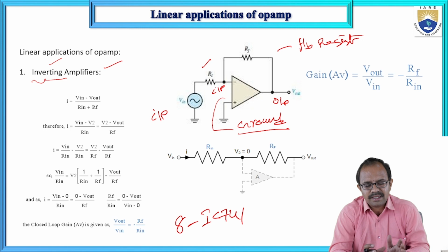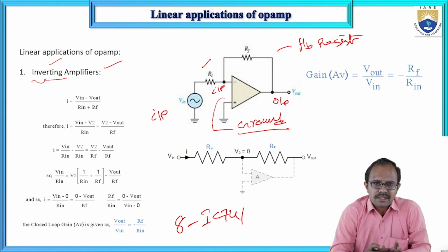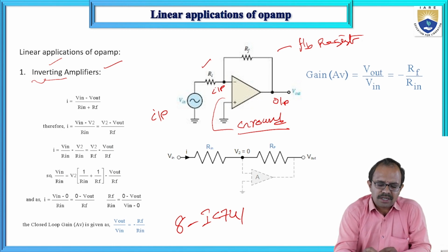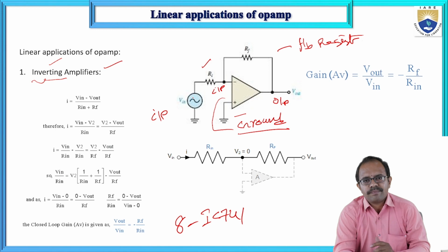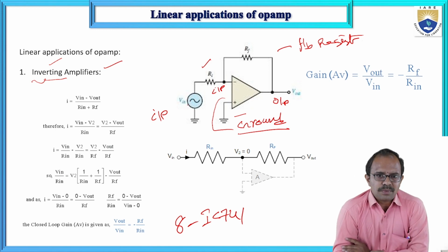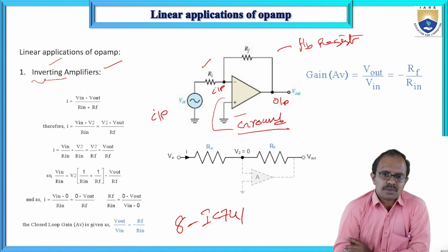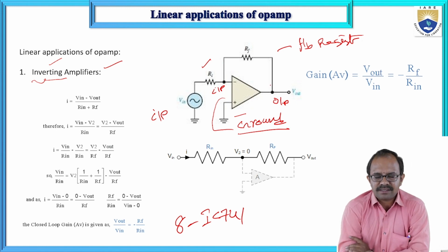So how we design the circuit here? This is inverting amplifier, so the non-inverting terminal is ground. No input or no excitation to the non-inverting terminal. And inverting terminal is getting excitation. That is, we are providing some source signal or input signal to the inverting terminal through some input resistance, which is RA. And then there is a feedback resistance that is connected.